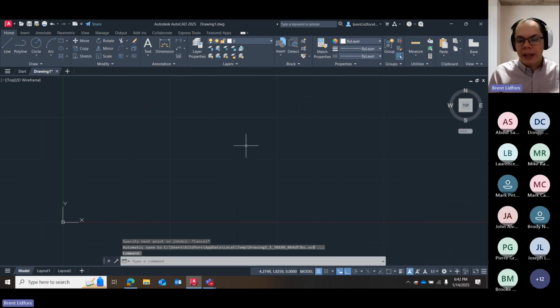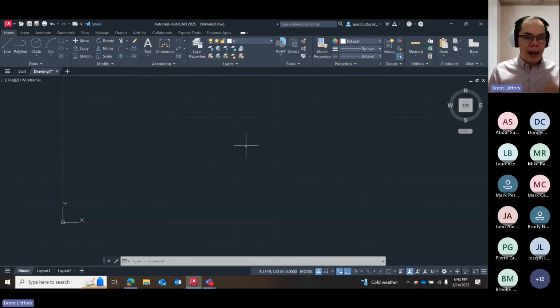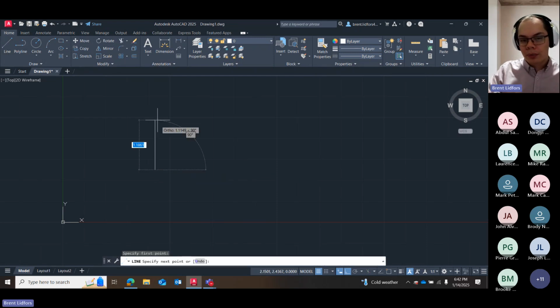Again, this helps with making a lot of right angles on drawings. Drawings are full of right angles, so we use them very commonly, which is why we have a tool specifically for right angles. That helps make sure that when I'm drawing, I'm not accidentally making it 90.05 degrees or something like that, because that can cascade into problems down the line. So when I use Ortho Mode, I'm making perfectly straight lines.